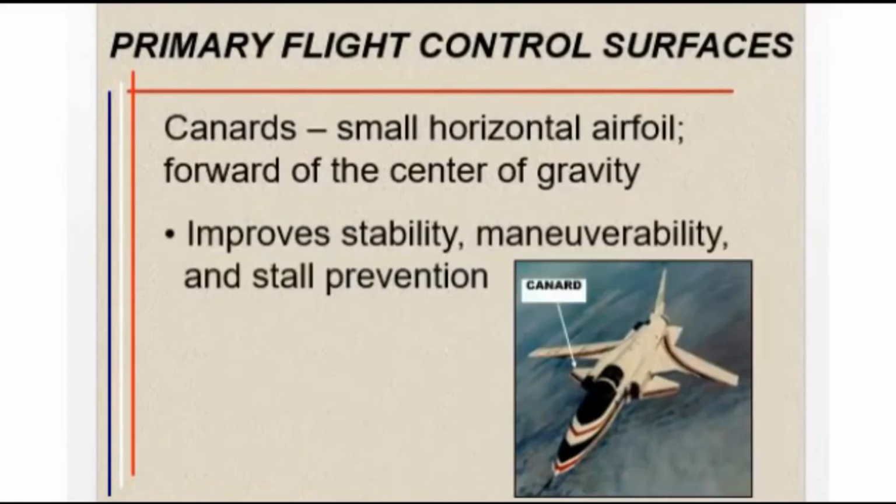Canards of an aircraft. A canard is a horizontal stabilizer mounted forward of the wing instead of aft. See figure 18. At high angles of attack, the canard creates high-energy vortices that wash over the wing, delaying boundary layer separation, hence stall.